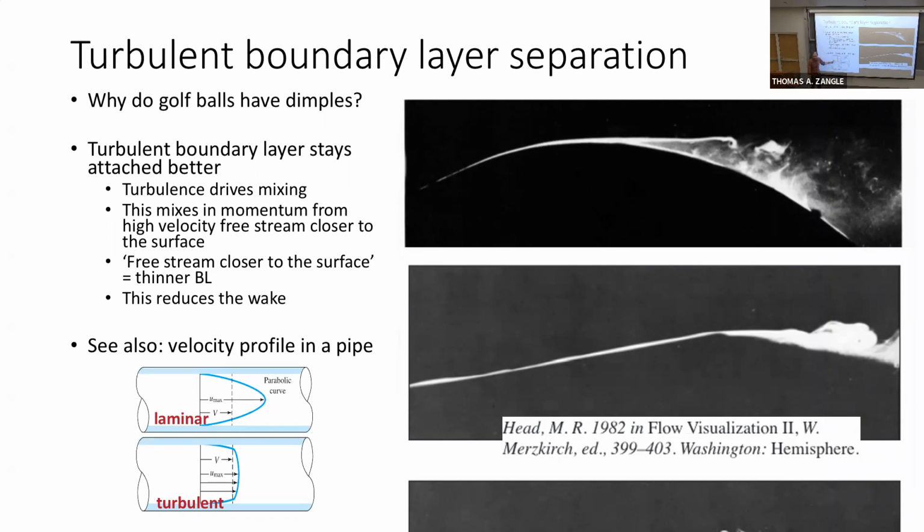We saw a similar thing give rise to the difference in velocity profiles within a pipe. Right, in laminar flow, we have separate lamina or layers of fluid that are basically flowing past one another, and not efficiently mixing with one another. So to think of this in terms of momentum transfer, the only transfer of momentum in the laminar flow profile was through these layers sliding on top of one another. And the layer on the bottom, if we're looking near this wall, is traveling a little slower than the layer on top.